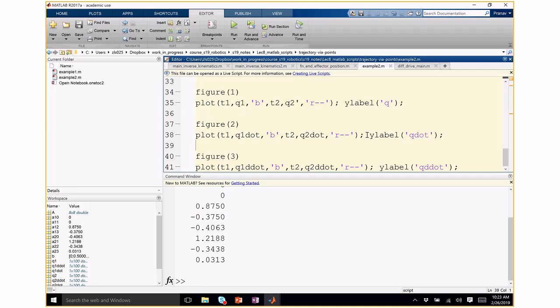What I did was finding trajectories for the joints. If you specify how you want the joints to move, you can create these profiles which are not jerky, very smooth, based on these conditions. You could take the same idea to inverse kinematics. Instead of specifying joint angles, you could specify the position of the end effector. So you could specify that x should go from position, let's say, 0 to 1 in a specific time, and the velocity, that is x dot, x double dot, have certain conditions, and the same for y. And you can create these profiles for x and y instead of q.